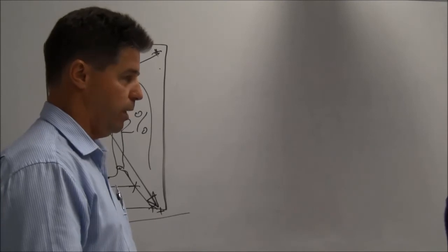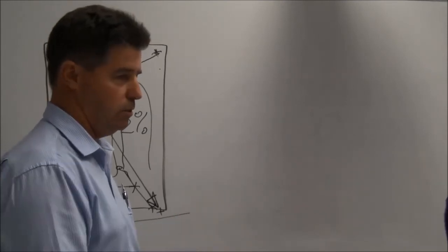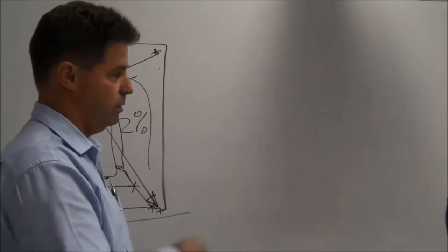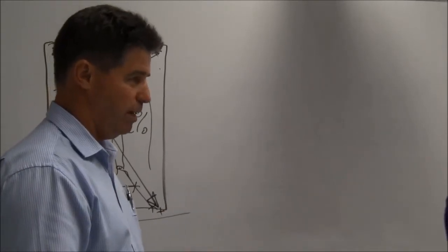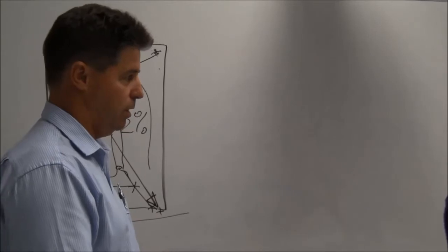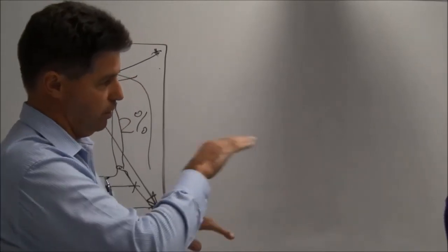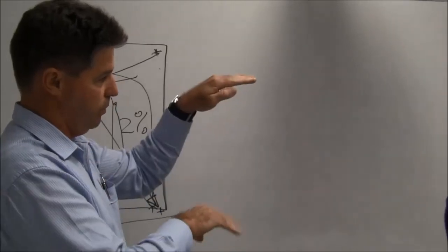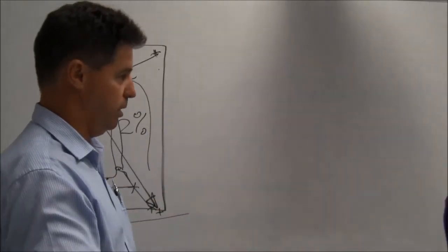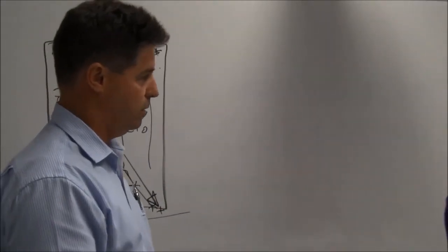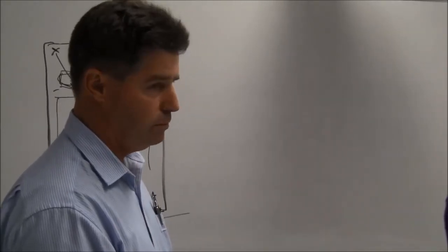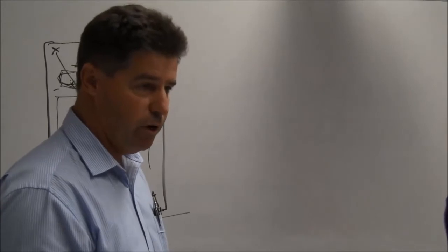Pipe grades, lengths, distances, all that sort of stuff has to be taken into consideration when you're going from a point. You have all seen an ARI chart, I'm assuming. It starts at 5 minutes, then 6 and 7 and right through. So if you've got 14 minutes, then you can go to 14 minutes and start using that. That's what you're sizing up. But that wouldn't include downpipes, would it? No, I'm saying roofs are 5 minutes.